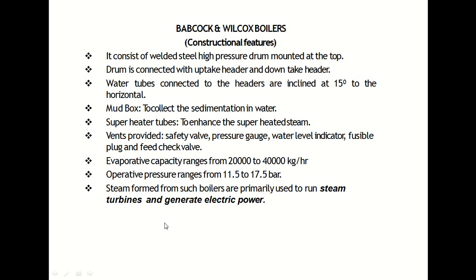Steam formed from such boilers is primarily used to run steam turbines and generate electric power, because a large amount of steam will be generated at the desired pressure. That steam you will use for power generation purposes. So this is the main application of the Babcock and Wilcox boiler.